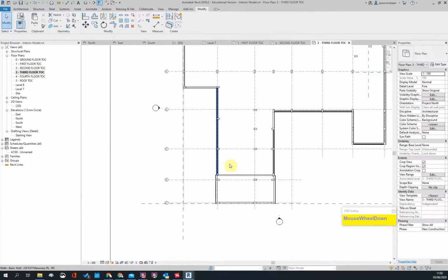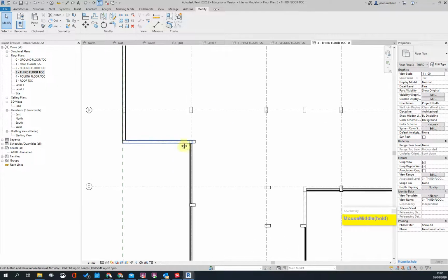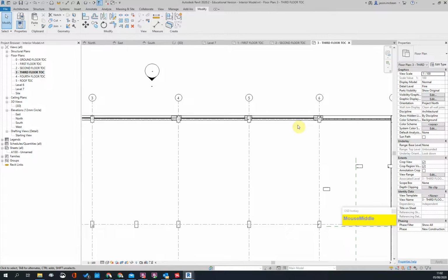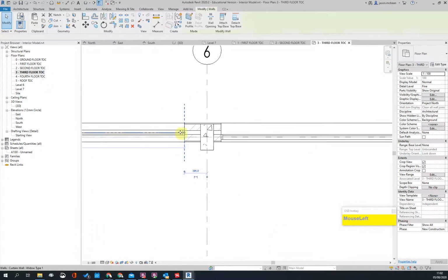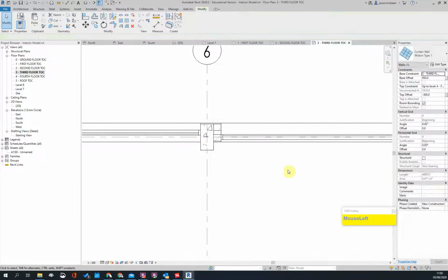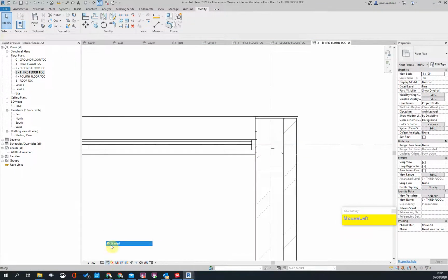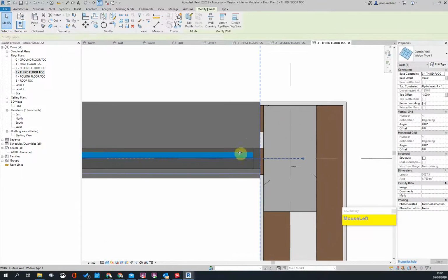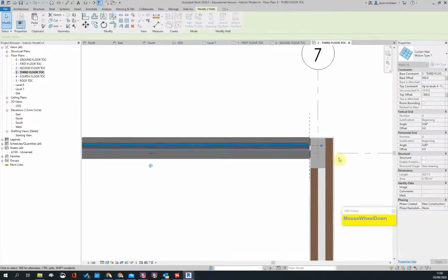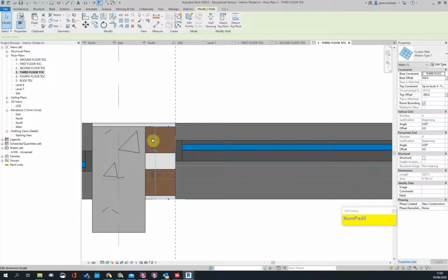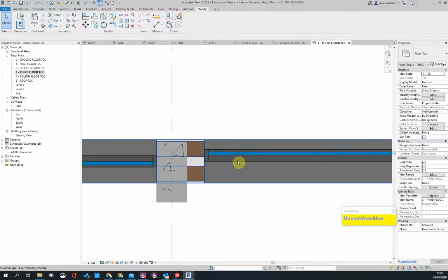My third floor, the windows are starting to look correct. We'll start putting in the correct mullions and when the windows occur. Okay, we'll start putting that information a bit later. This will go until there. Okay, so I just need to align these and let's just say shaded for now. This will need to move and that's just offset from the face of the column. That'll be 105.